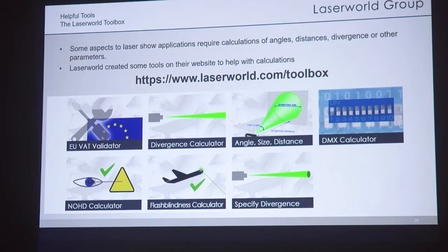There is one hint that you should consider, and this is if it comes to graphics projection. Never calculate the maximum possible scan angle of your laser system as the maximum angle that you would put in the calculator. Maximum use 60% of the maximum possible scan angle.